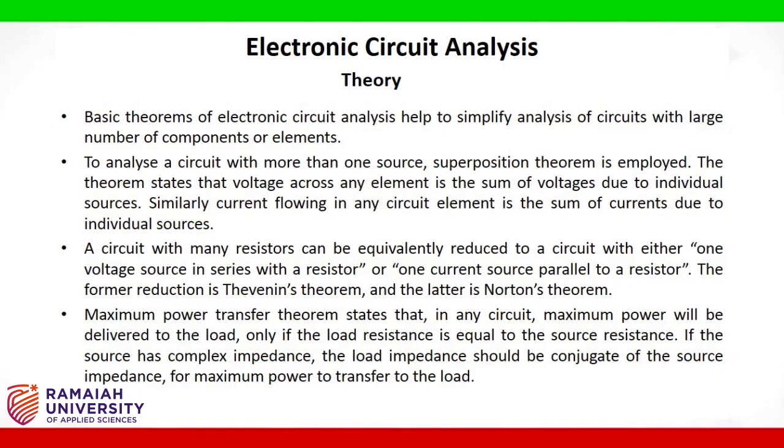A circuit with many resistors can be equivalently reduced to a circuit with either one voltage source in series with a resistor or one current source parallel to a resistor. The former reduction is Thevenin's theorem and the latter is Norton's theorem.